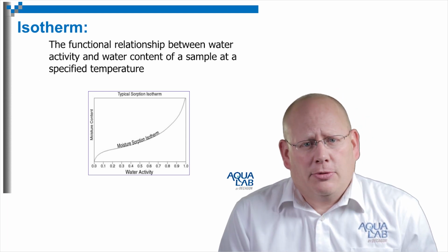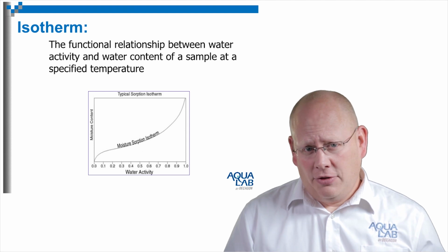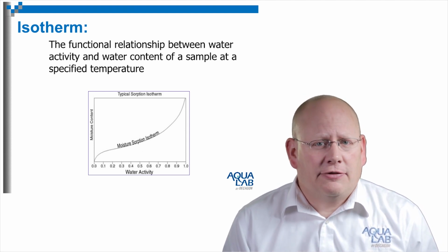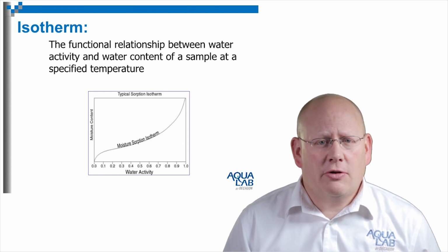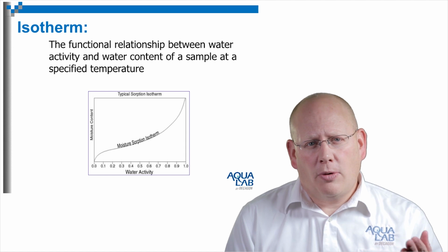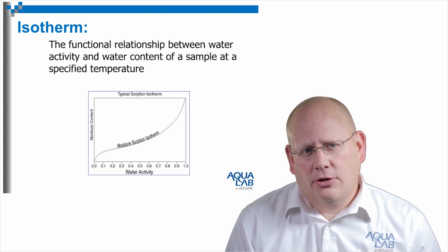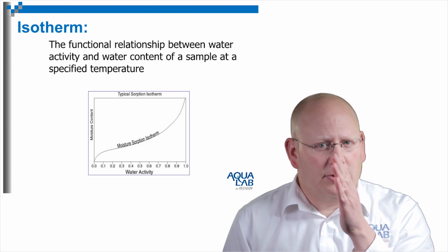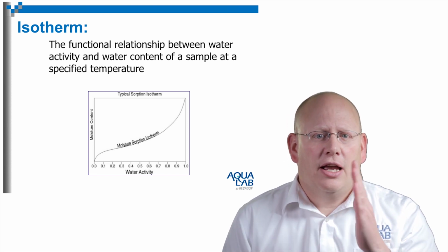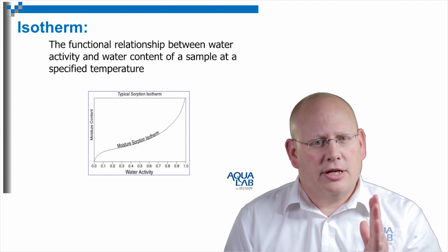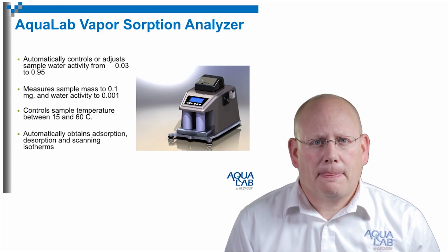It also provides valuable information about the nature of the material, how hygroscopic it is, how it will react if it's combined with other ingredients. All this information is provided by this moisture absorption isotherm. And I'll reference this several times as I go through the rest of this talk. But it's important to have this understanding of the relationship between water activity and moisture content. Again, water activity being the energy, moisture content being the quantity of water.